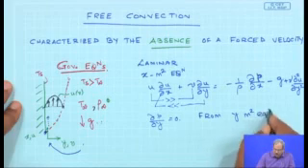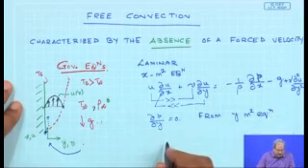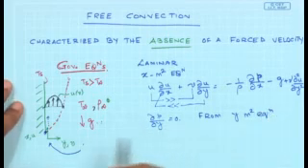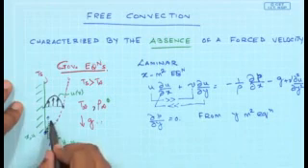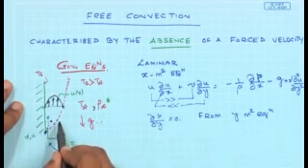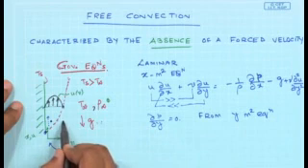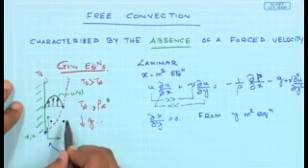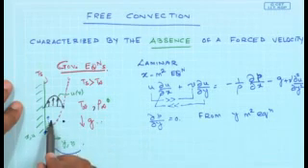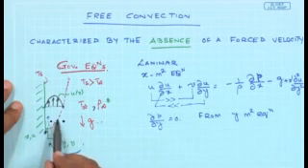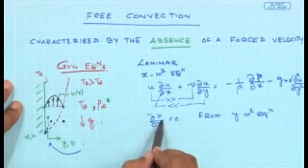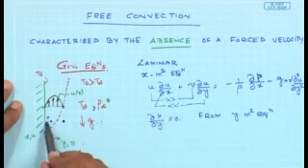So the pressure gradient at any point inside the boundary layer must be equal to the pressure gradient in the region outside the boundary layer. So the pressure gradient at these 2 points would be identical, since ∂p/∂y is equal to 0 and p does not vary in the y direction.